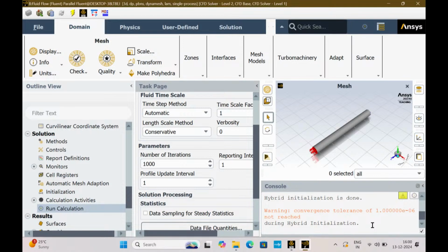For us it is not showing because we took some different. Okay, then it's good. So for this mesh, maybe, you will have to play with the mesh. Like for only the fluid flow part, it worked fine, but maybe for this part it will not. But the solution will anyhow converge, because the convergence criteria is very loose, 10 to the power minus 3. So you can visualize this thing, but quantitatively it will not be correct. So just close this after that.